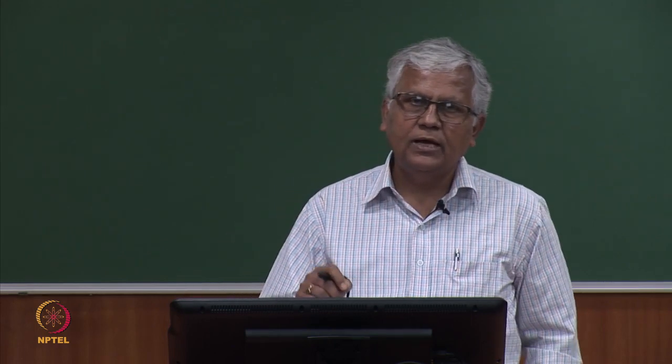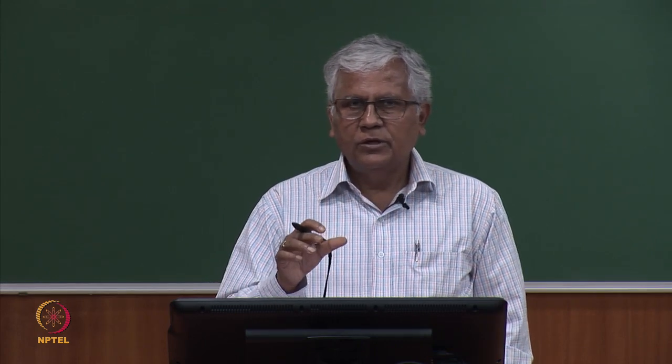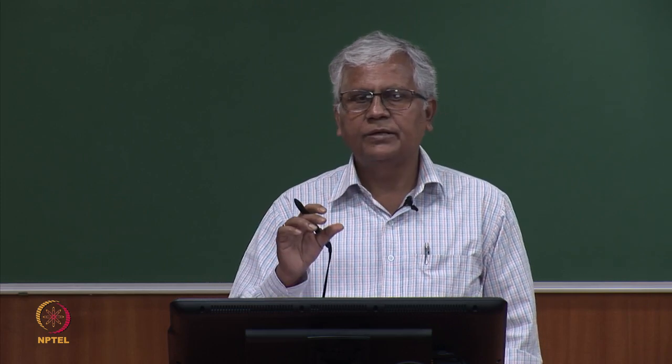Spindle is rotating, traveler also is rotating, both of them rotate together. The bobbin is on the spindle, that means the bobbin speed and the spindle speed are exactly the same. So, bobbin rotates at the speed of spindle. The traveler also rotates, not at the speed of spindle, sorry, the traveler will rotate at a lesser speed than the spindle, that is, the traveler will always lag.